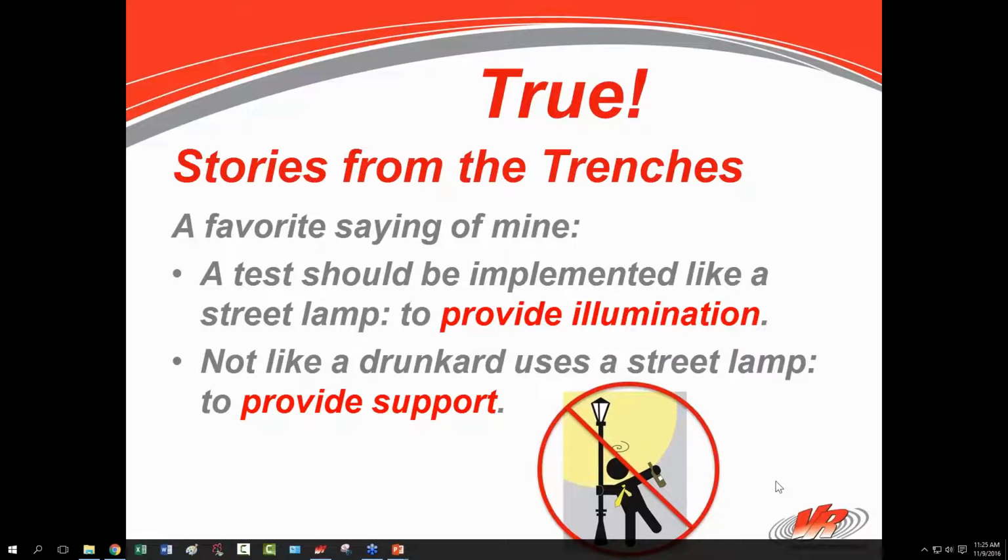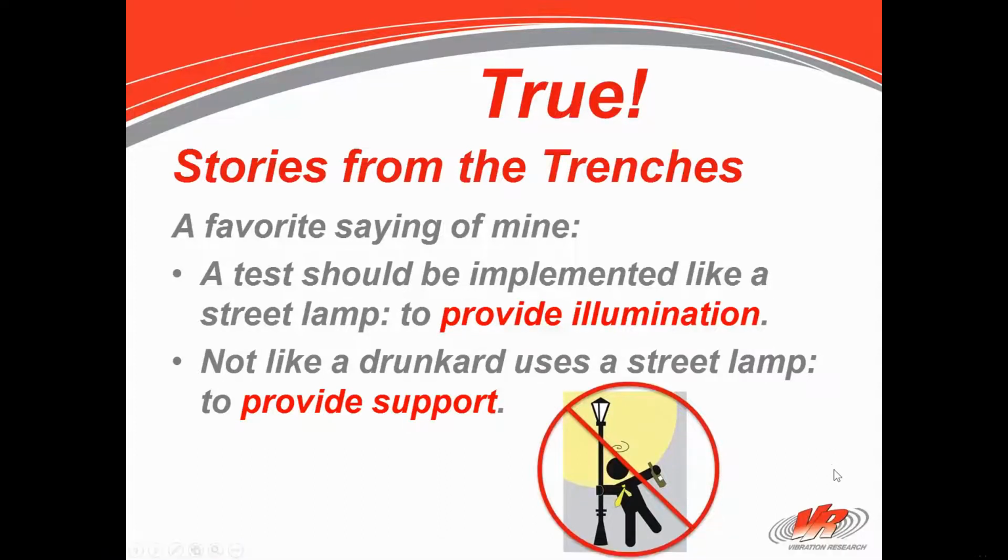Now, how do you do it for the test? Well, typically, you're going to put accelerometers on your product. Your test description should tell you where to put the accels. You're going to do the sweep. You're going to do a transfer function, and you're going to see what the transmissibility is, and the resonance will be located right at a particular spot. We can do a whole other seminar on dwelling on resonances. There's a bunch of things that you have to pay attention to. When you sweep up, when you sweep down, and when you hold, the controller is going to indicate different frequencies for each one.